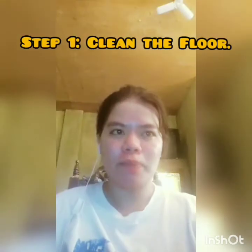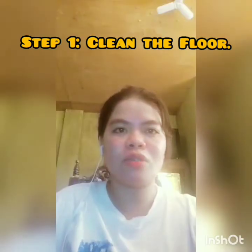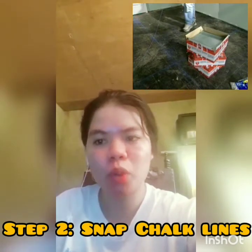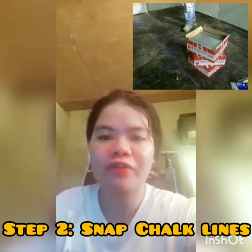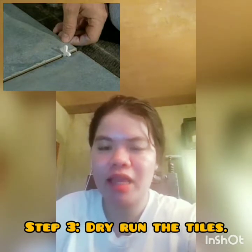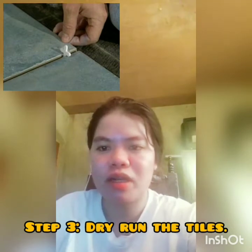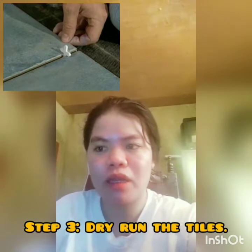So first step, you must clean the floor of dust and debris. This ensures that the tile surface will be level. Make sure to find the center of the room and snap two chalk lines that intersect exactly in the center of the floor. Step 3. Dry run the tiles. Before starting the project, start with a dry run, laying out the tiles and spacers. This determines where to start the process and helps determine the width of the grout lines.